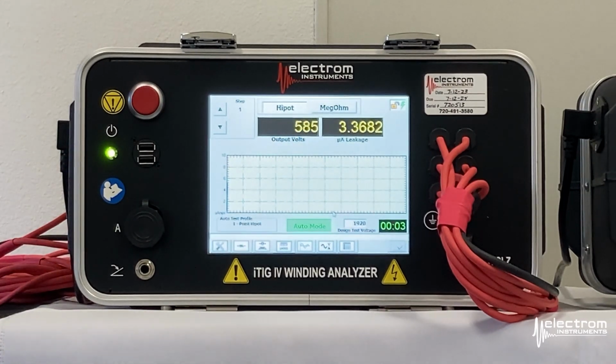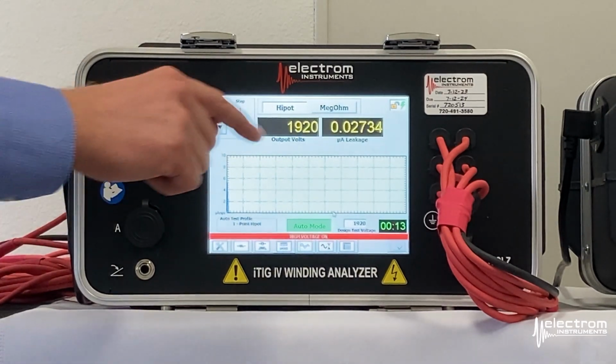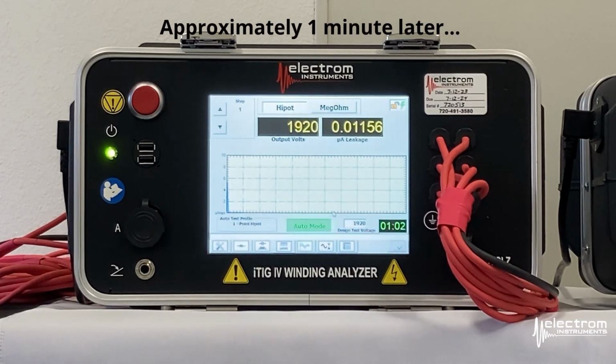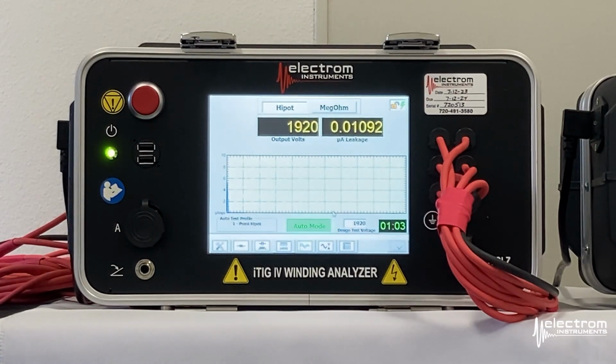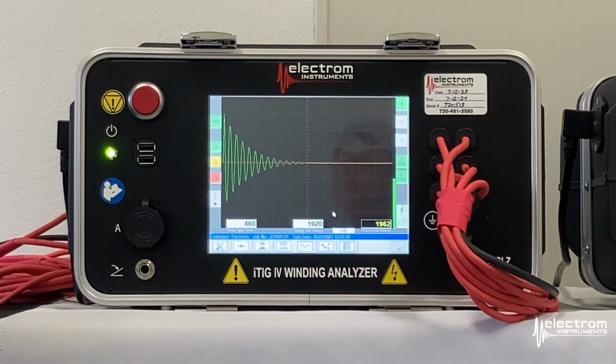We passed our Megohm measurement, so we're now on to the Hipot test. It automatically ramps up the voltage to our design test voltage, 1920 in this case, measuring the leakage current, and we will again sit here for 1 minute before discharging. After sitting here for a minute, the instrument will now automatically discharge the windings. You can see the bar in the bottom here going from red to blue, and we move on to the